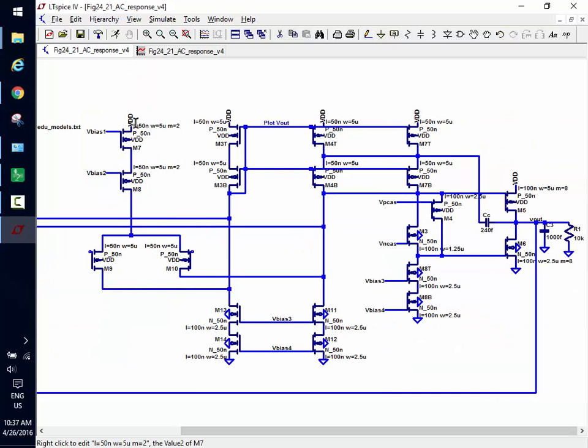Here, what I have is a current flowing down through here. This is a current source of 10. This is a current source of 10. And I've got 10 flowing through here. But this node, which clamps this node at VDD over 2, doesn't have any place to flow, right? There's no reason for this to turn on, so it can shut off. You follow me?